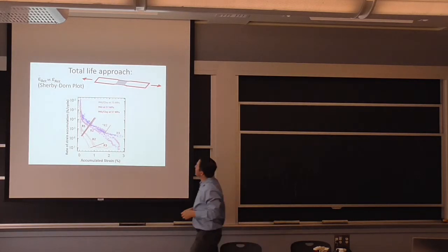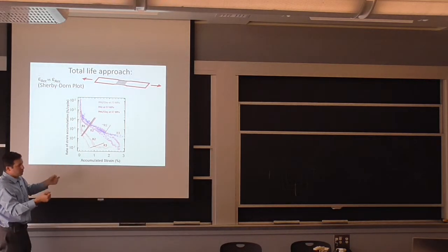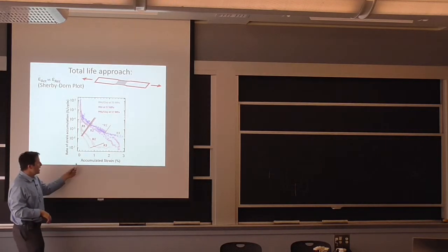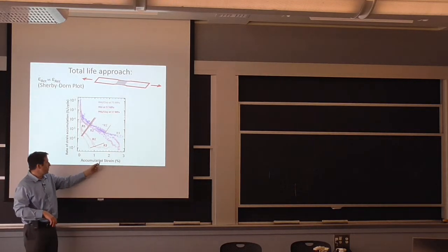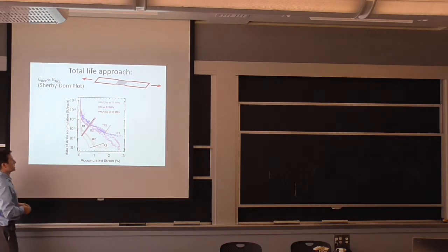So what we're looking at here is essentially some specimens that were loaded in tension. It was cyclic load, but the effect would be similar if you use a constant load. It just goes faster. That's the advantage here. So you're looking at the amount of strain, and it's relatively small. We're only looking about 1–2% strain here, because nylon is relatively low viscoelasticity at ambient temperature.